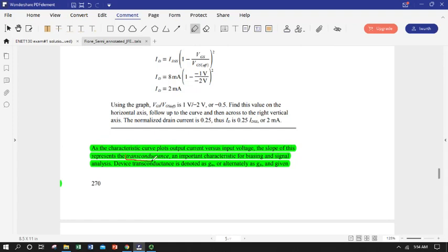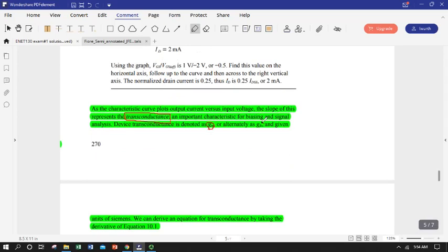Okay, last but not least is a final spec term. It's a bit of a vocabulary term, but it's just another handy way of using that gate to source voltage, control voltage, versus our current. It's a term called transconductance, and the symbol is a little g sub m or little g sub fs. So you'll see these on spec sheets.